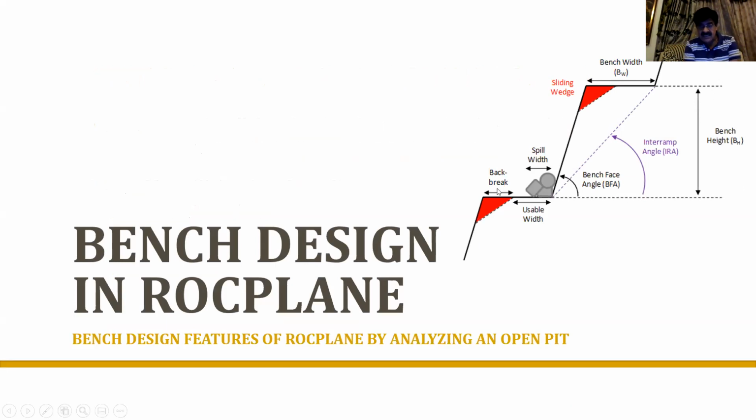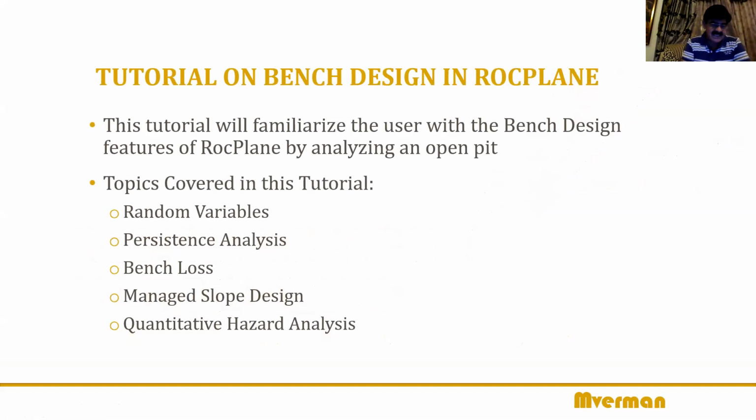The instability, the failures can happen here, because of which this back break, what's called back break in mining engineering, has to be kept in mind when you want to design the minimum width of the bench, because this part will eventually be lost, for several reasons. Wherever you have sharp corners in rock engineering, you can expect problems there, where stresses are likely to exceed the strength at the corners. Anyway, we'll come back and see this.